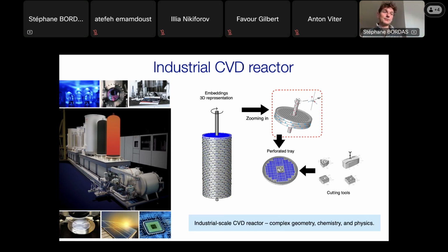And what you don't want is that you have a surface that looks like a wave, that's totally wiggly, because if you have a wiggly surface, well, obviously it's going to create asperities and sharp changes in shape, and that thing is not at all what you like, because if you have that, then you will create concentrations in stress when you use the tool, which goes opposite to what you are interested in, which is to create a tool which is resistant and able to sustain large loads without breaking and without wearing off. So that's what you're interested in here.